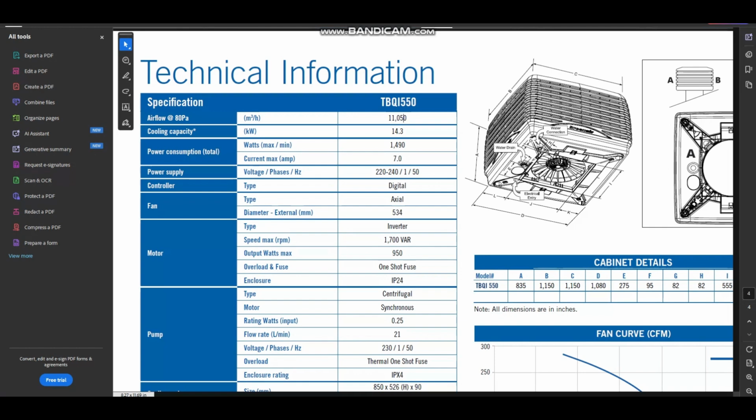However, because the water is being used to make direct contact and cool the air, your humidity is increasing from 30% up to between 70 and 80%. Now, this is fantastic for human consumption. Skin, eyes and sinuses all prefer slightly more moist air. Anywhere between 50 and 80%. It tends to vary from person to person. Some equipment might benefit from these humidity conditions as well. We've done so many print shops over the years where the printers function optimally at between 70 and 80% humidity.